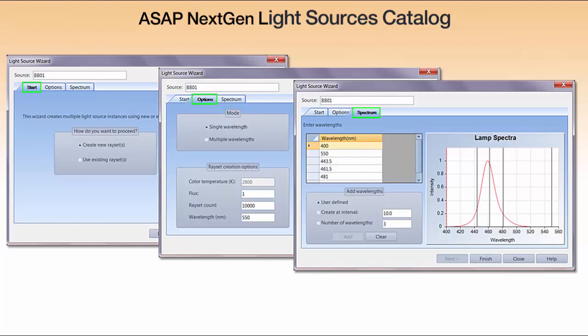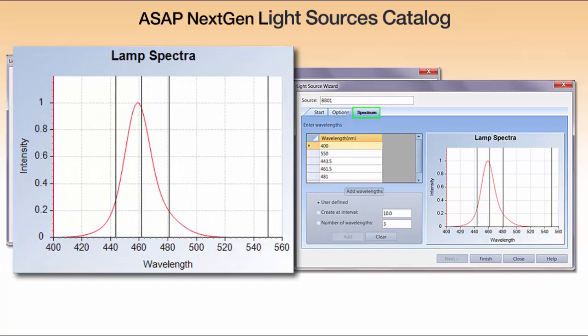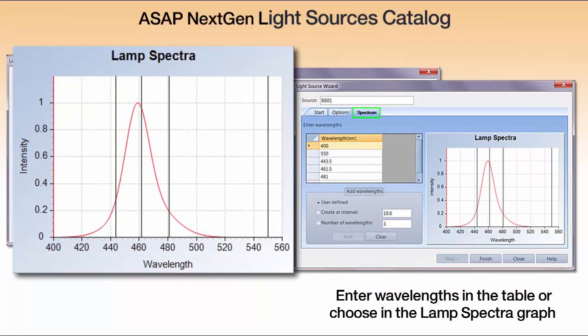After we do this, it actually creates ray sets to represent the spectrum at the wavelengths that we have chosen as samples. And once those have been created, we can then attach those ray sets to the model. We can choose to model a number of wavelengths at once. We can choose to model a single wavelength initially for debugging our model and then add other wavelengths later. We have many options here. This just shows the dialog for attaching the actual data to the model. And when we're done, we actually see the sources pop into our viewer. So we pre-calculate the rays so that they don't have to be done dynamically every time.